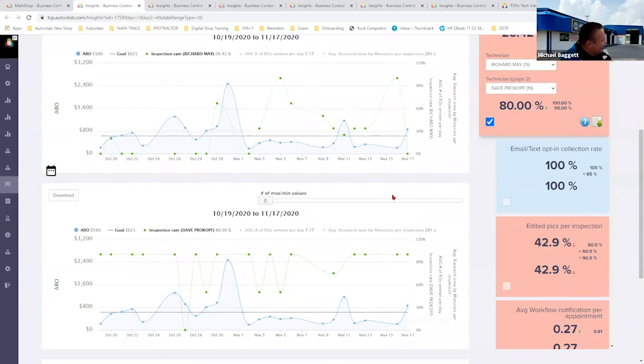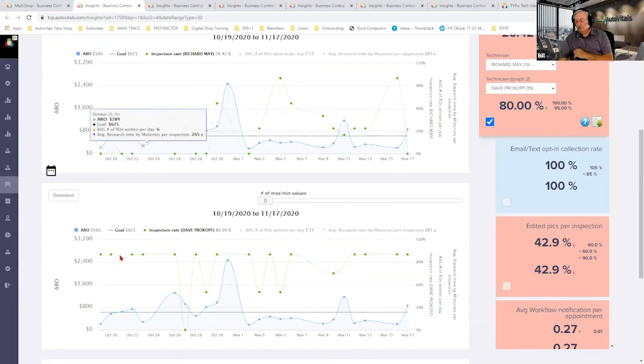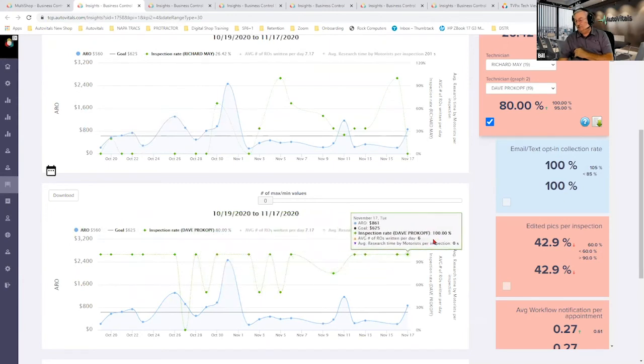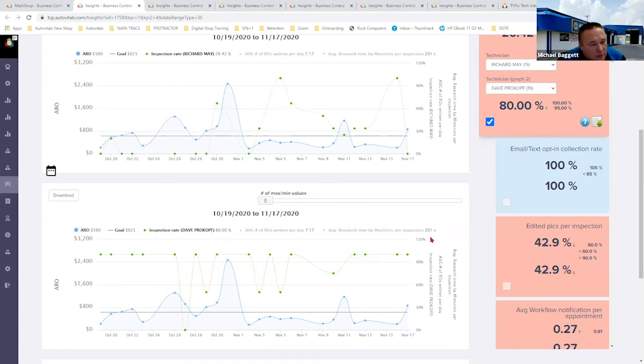It's kind of interesting what you'll find out when you just start, and it's just like diagnosing a vehicle. You're looking for the dropouts or change, or what I call glitches, and you can see here that we're running smooth, and then all of a sudden we got some glitches and we run smooth again, and now we got some glitches again, and now we're running smooth again. From a technician, I'd call that a misfire.